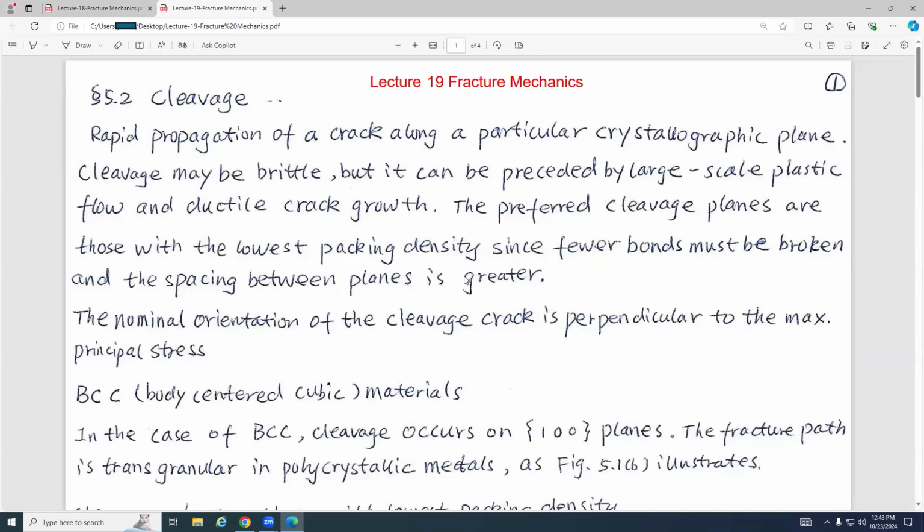So microscopically, when we say the material breaks, what comes into your mind, guys? Can someone tell me? For example, this is a piece of paper. It is broken. What does it mean? Can somebody tell me what is broken? Okay, the bonds fracturing. Yeah, bonds break. That means before I break this material, along this line there are atoms connected by bonds, right? Breaking means that by some means I break the bonds so that these neighboring atoms are separated. So this is the physical meaning of fracture or breaking.